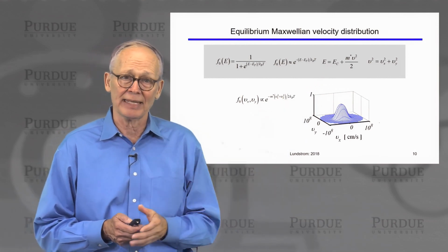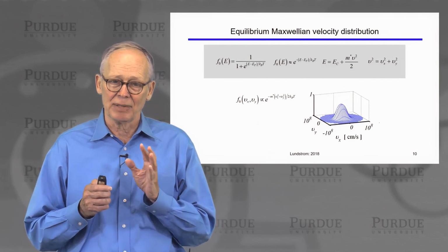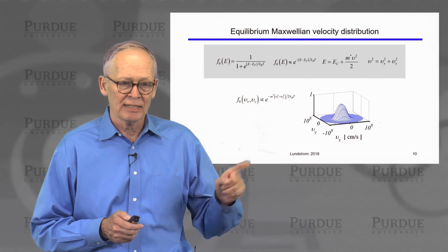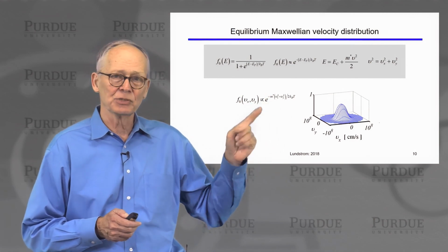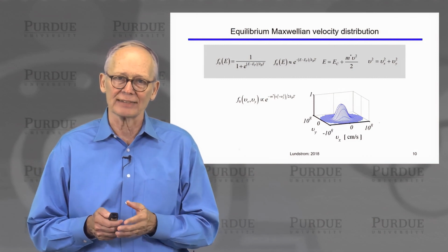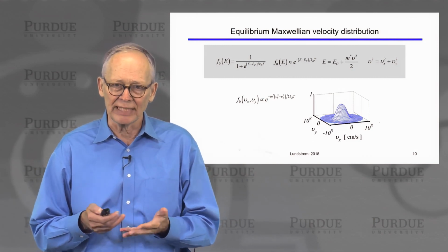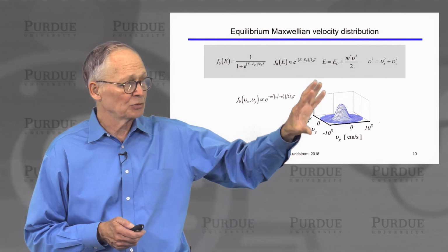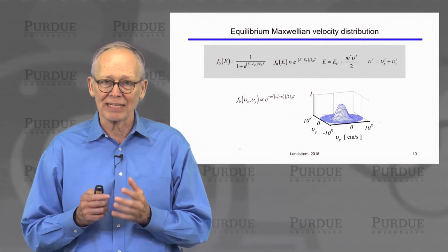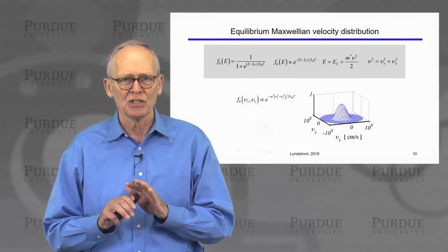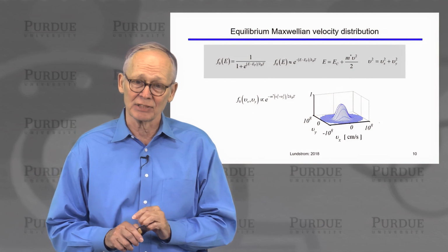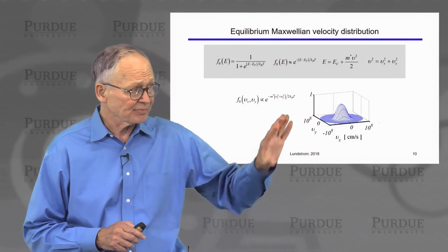If we have a parabolic band, E is equal to the bottom of the conduction band plus 1/2 mv squared, the kinetic energy. And we conclude that the distribution of velocities should be a Maxwellian distribution of velocities in the 2D plane of the channel. So this is what it would look like in equilibrium. We'd simply have a symmetrical Maxwellian distribution of velocities. No average velocity in any direction, because there is no average velocity in equilibrium.